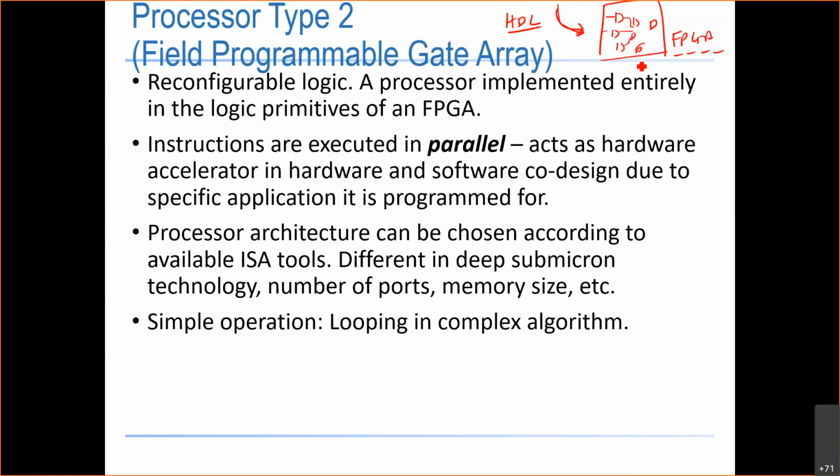The good thing about FPGA is that it is reconfigurable. And then the other thing is that you can build your own circuits in parallel, so you can do parallel processing. And then it is application specific. You can do whatever you like. You don't have to buy a special processor to do image processing. You can do your own image processing algorithm and then download it to the FPGA board. The circuit will be downloaded there, and the FPGA will be configured to do whatever you want. So in other words, rather than build your own circuit yourself, you can program the FPGA chip to represent your circuit. That's the advantage of what we call an FPGA board.